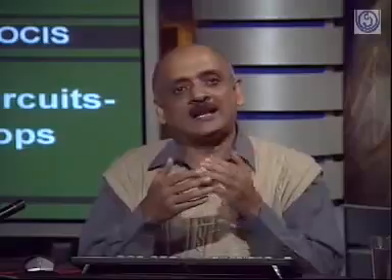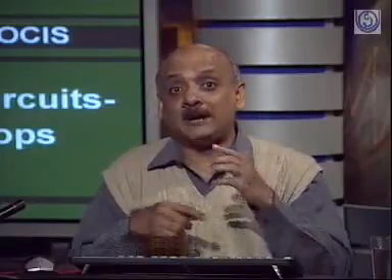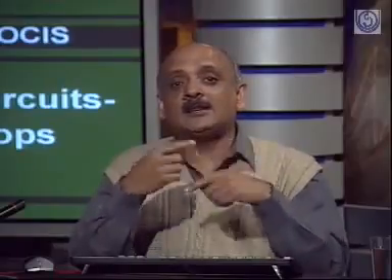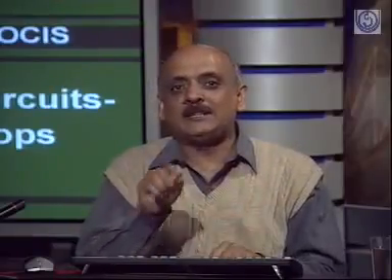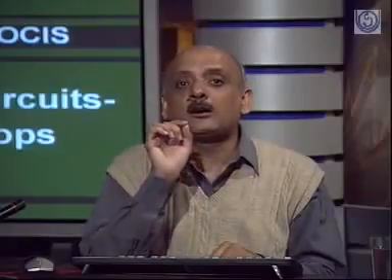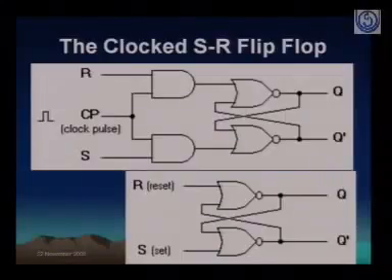Okay, so this was fine. This was a basic latch. It can change its state at any point of time. The problem is that the circuit may become unstable. It can loop. So that's why we need a clocked SR flip-flop. So we need to bring in the element of a clock, right? So this was the basic latch. You can see the basic latch over here.